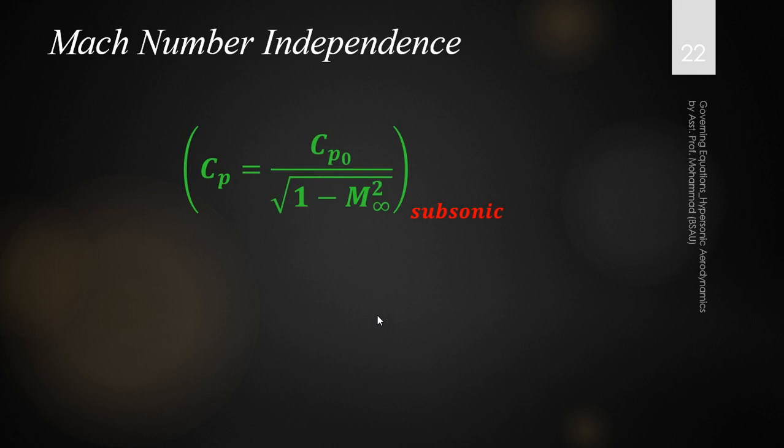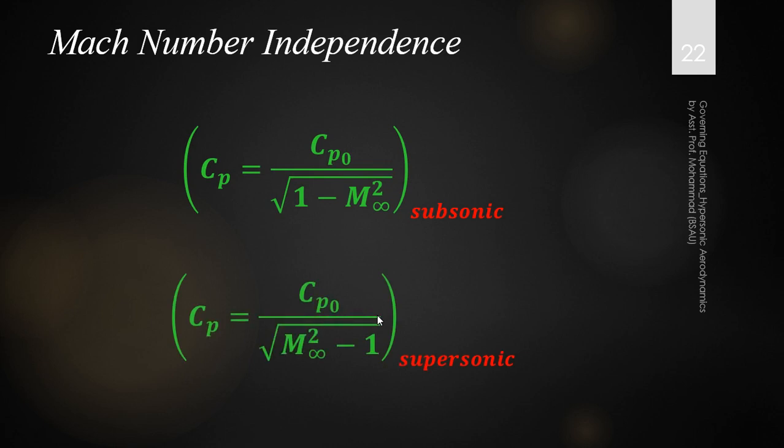Let us consider the case of flow over a wedge and a cone of something like 15-degree half angle. It's clear that for supersonic Mach number, Cp decreases rapidly as M infinity is increased. We say that if M infinity increases for the subsonic flow, it actually decreases rapidly.